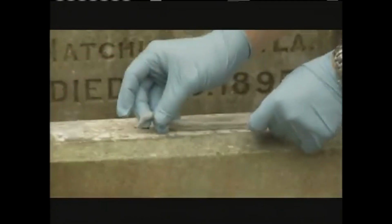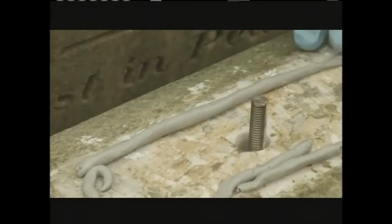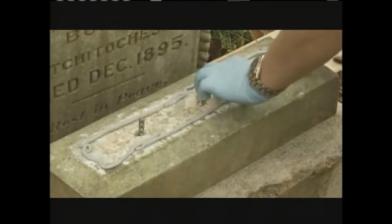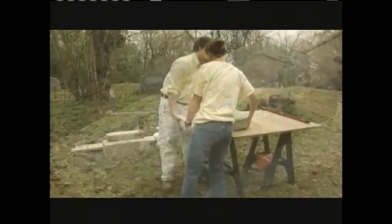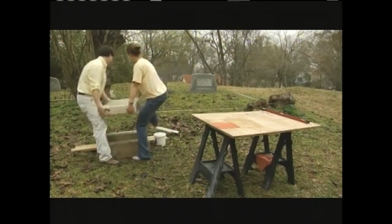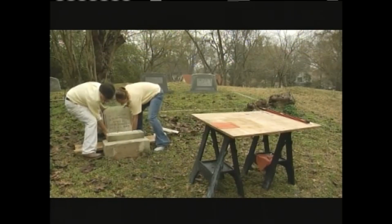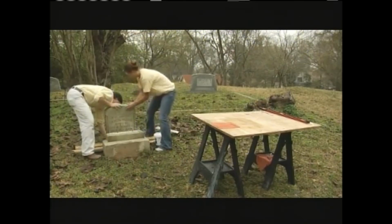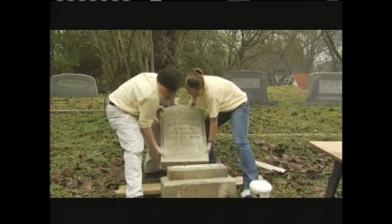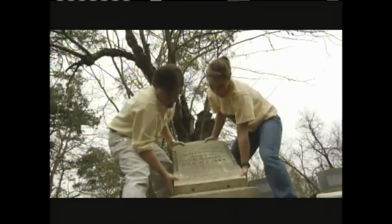We start by laying the compound around the edge of the stone, about 1/4 to 1/2 inch away from the edge of the headstone's base. Once the stone is set, the compound will flatten and push out of the sides slightly. Now it is time to place the headstone back on the base. It is important again to lift with 2 people. These structures may be surprisingly heavy, yet delicate, and a great amount of care must be exercised when moving and handling them.